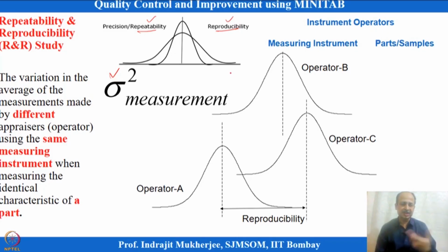What is repeatability? If you are measuring the same parts, there will be some variation in the measurements. The same operator measures repeated times, and the instrument will have some variations. That contributes to the repeatability aspect, which is the error in the instrument. So this is basically common variability. Everywhere this type of variation will happen, because if I use the same instrument a second time, sometimes readings deviate somewhat, and that amount of variability is represented by this measure known as repeatability.